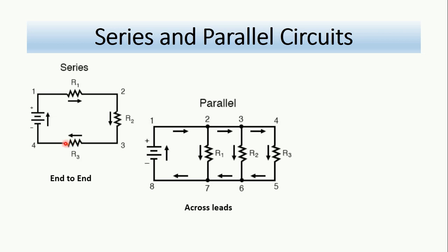So in order to make this complete here, we say that the voltage drop across the parallel resistors must be equal, so VR1 equal VR2 equal VR3, and the total current going to these branches will be divided such that the sum of the currents in all resistors is equal to the total current going to these branches. And this is actually Kirchhoff's current law applied at this node 2 here, where the I total will be divided into IR1, IR2, IR3, and the sum must be equal to the I total.